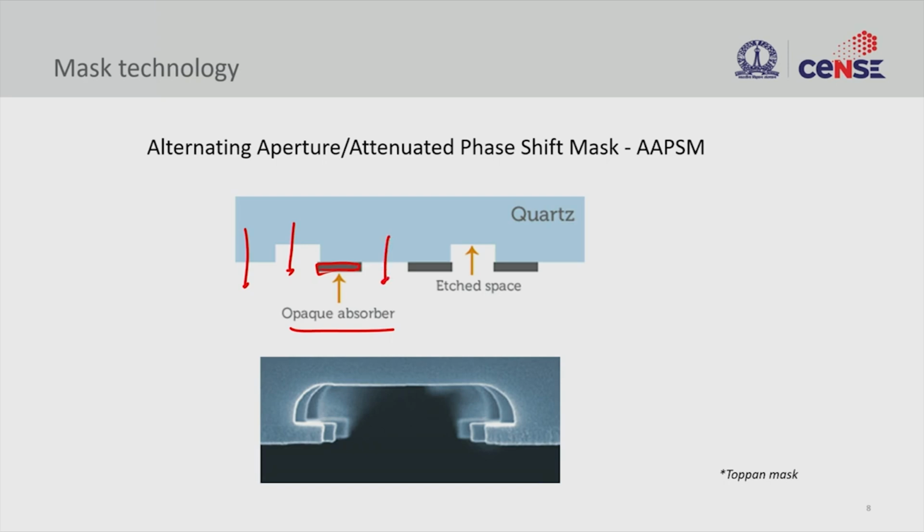So what we are trying to achieve here is you get the light modulation by using phase shift here, and in this case you are using just the power difference between these two. So a complex mask could be built by using this technology to achieve better resolution. The only downside in this kind of advanced mask is the circuit design itself. When you have structures from different devices coming very close to each other, managing those phase shifts and the absorption is going to be a challenge.